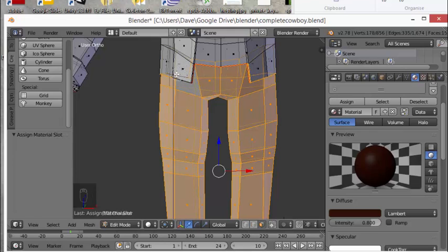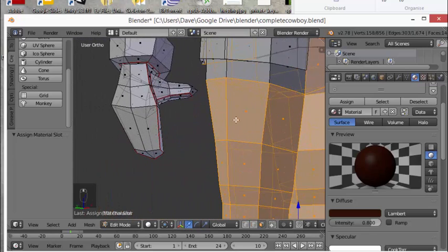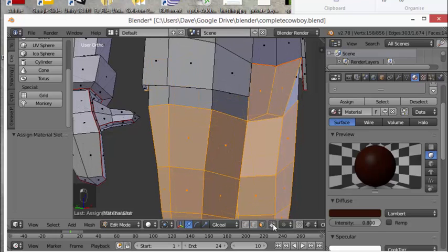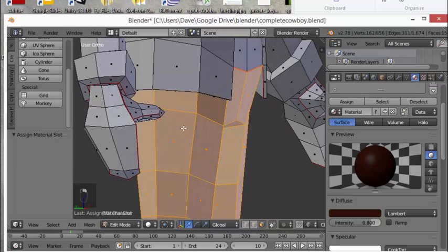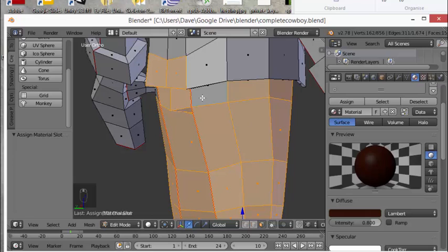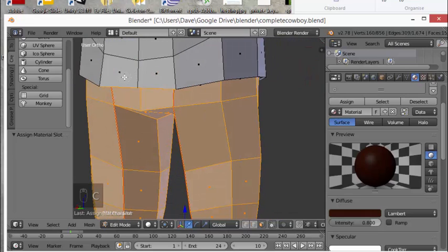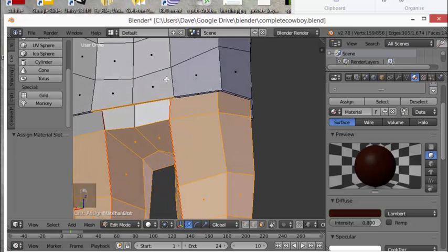And we need to get those undersides of the jacket. We don't want them selected, they're not part of the trousers. So it could be, shift right clicking would probably be the answer to pick those up again rather than the brush, but we'll persevere. We've turned X-ray mode off, which helps the brush select tool to work better. We'll spin him round and have a look. We've got a couple of pieces of jacket, so we'll middle mouse click those off, like so. I've got a little bit of the underside of his jacket which has proven awkward to deselect.